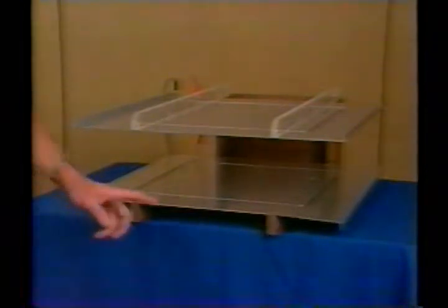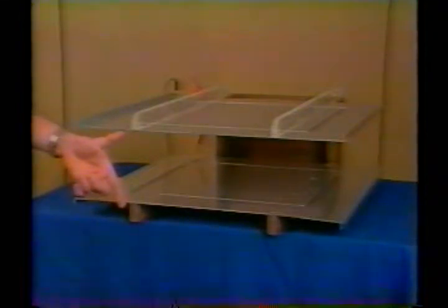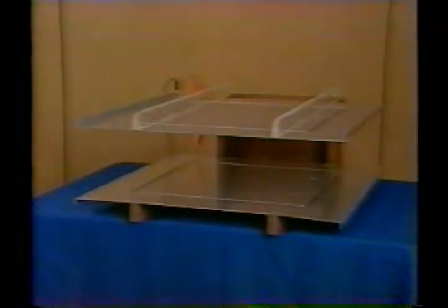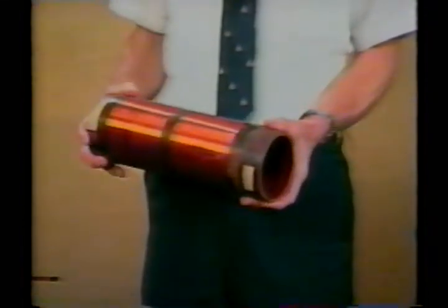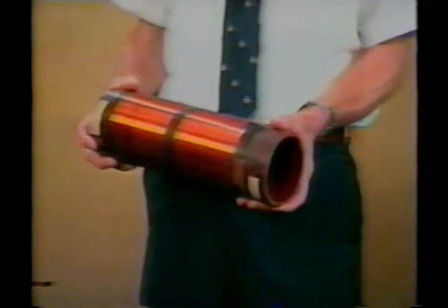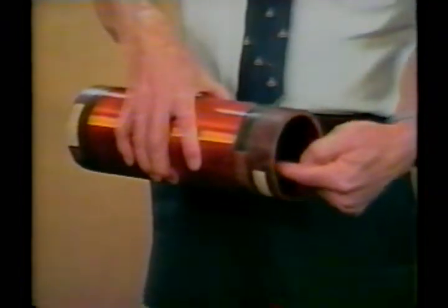This solenoid is large enough that we can poke around in it with a magnetometer probe and see how the magnetic field is actually distributed when the length is finite. The solenoidal coil consists of n turns, essentially uniformly wound over the length d, each turn carrying the same current I. The radius is a. The current I is essentially phi directed.